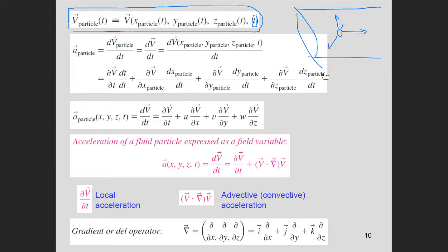In the Lagrangian, you have to follow each particle alone, separately. In the Eulerian, you build an ensemble, a small finite volume, and then you study the movement of flow in this finite volume, and then you integrate.